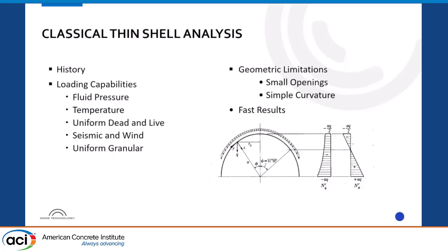This is one of my favorite pictures right here, because it shows you how to calculate your lateral stresses and your vertical stresses in a dome shell for a projected load on top. Is that projected? I think it's a uniform load on top of a dome. And so you can solve that pretty quickly by hand and get a feel for what the stresses should be.